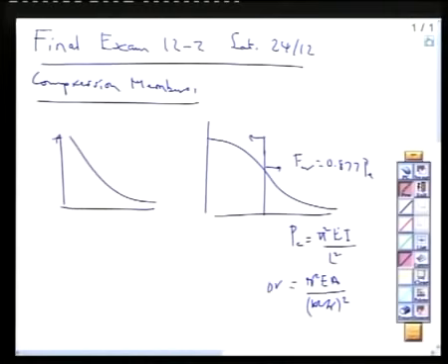This is F critical. And this is KL over R. It is common sense to say that at F yield, when the member reaches F yield, it's no more elastic. We go into an inelastic range, and the curve will be like this. However, this is F yield now, and the curve starts from here going into an inelastic range.